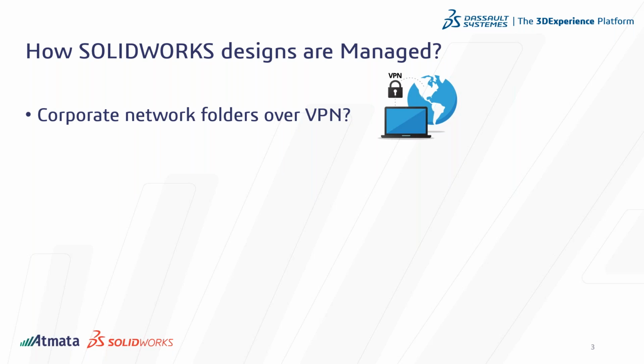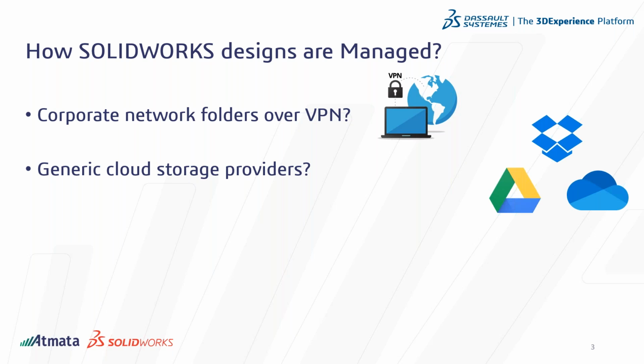So let's move to the next one. Cloud storage. I hope everyone must have guessed by now. These solutions don't understand the interdependencies that can exist between SolidWorks files. So if you move files around or between different folders outside SolidWorks, you can easily get into a mess. Assemblies and drawings suddenly can't find the dependent parts when you attempt to open them. These issues can happen with this type of solution.